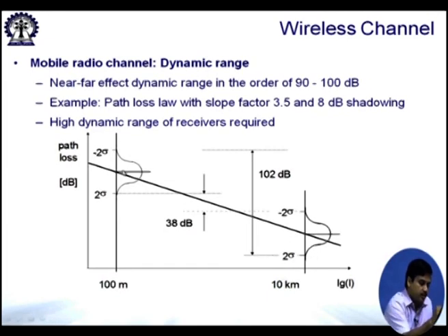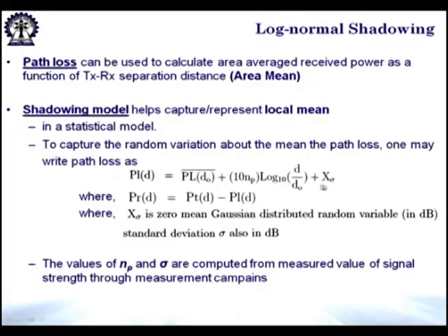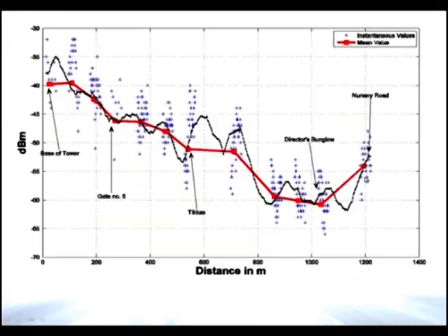That means, when you are close to the base station, you would get fluctuations where the maximum received signal strength would go even beyond that predicted by the average because of the random fluctuation. If you see this model, there is random fluctuation. To support this, if we look at this data, the signal strength did not decrease monotonically, it can go above, and if this is the average slope as pointed by the cursor, it could go below the average.